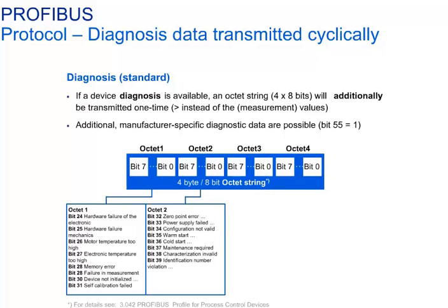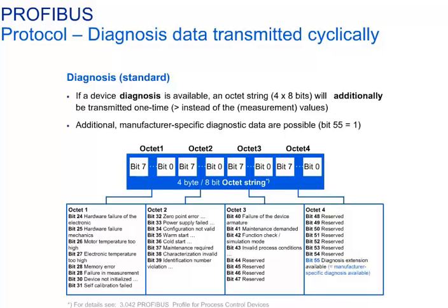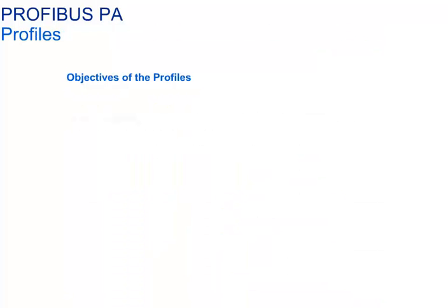In the boxes you can see here, the standard diagnostic data for the field devices are listed. The great user benefit is that for the first time, profound information from the field devices and their connected peripherals like valves, pipes, and so on can be transmitted to the distributed control system. Predictive maintenance is thus made possible, especially due to other manufacturer-specific field devices' diagnostic data. This kind of data transmission is not available for 4 to 20 mA devices.